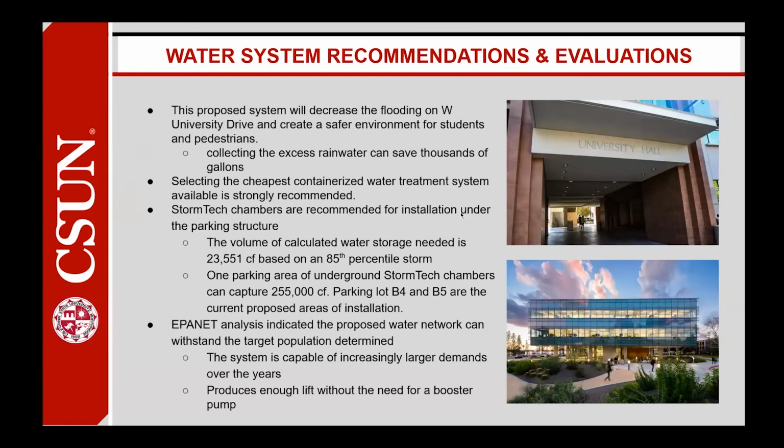Right, so leading into the water system recommendations and evaluations, we decided that this was the most efficient water treatment system available. As the area is relatively small compared to most projects in magnitude, StormTech chambers were recommended for the installation. The volume of the calculated water storage needed is based on an 85th percentile storm.